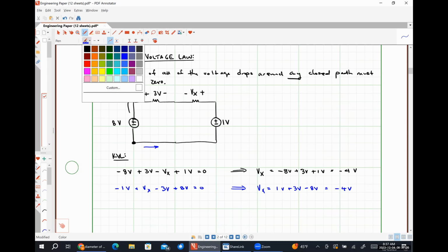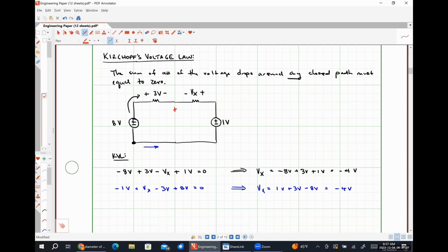So, for example, let's say that I defined the voltage drop Vy here across the middle of the circuit. This is the voltage drop between 2 points, so it's perfectly fair game, but there is most decidedly no current flowing down through that middle area. Any current flowing in this circuit is either circulating clockwise around the perimeter or counterclockwise around the perimeter.